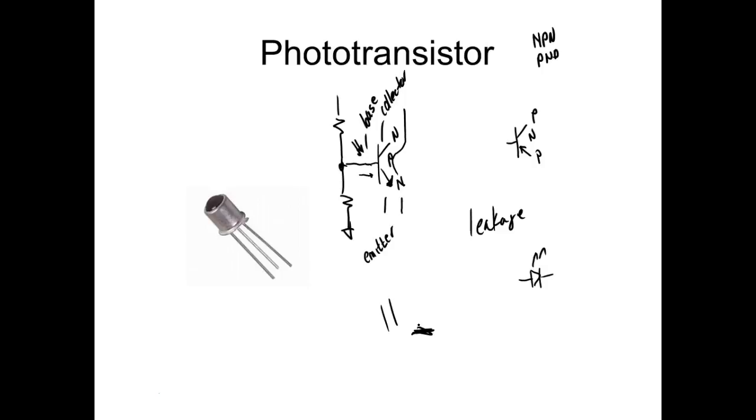So I guarantee you this uses a phototransistor. The remote on your TV uses the what? Phototransistor as the receiver. You're right, your transmitter is infrared. Why we make it infrared, of course, is there's not a lot of infrared in the white light spectrum, and plus, it won't be annoying when it flashes.